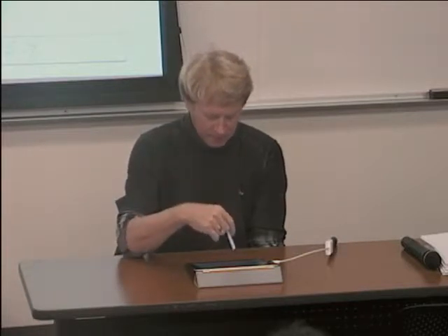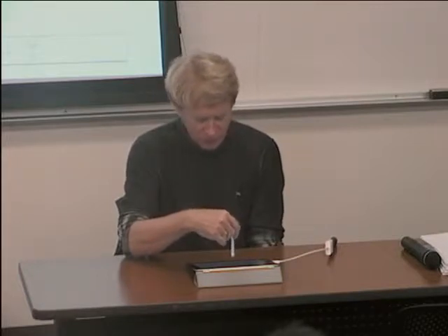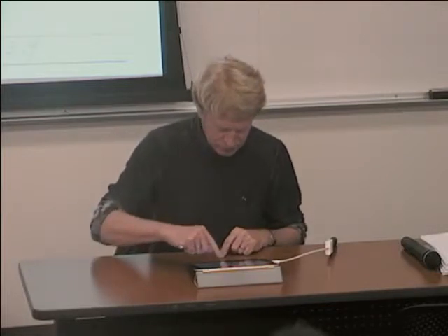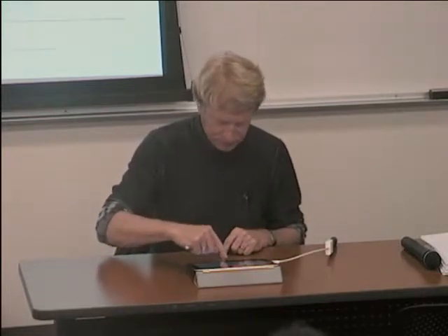There's no cost for NRE because everything is reused. No design effort. The only thing that changes is I have more chips per wafer. And the cost per wafer has changed. Instead of being 5K, it's 10K. But now I can compute the number of chips per wafer. It's a larger wafer, so I get 640 chips per wafer. And you multiply by the same yield, 0.85, and 10K. Bottom line is the price goes down from $24 to about $20. Again, we're not really looking at all the details. If there's a computing error here and there, we didn't really look at that too much. Quite liberal in grading this.